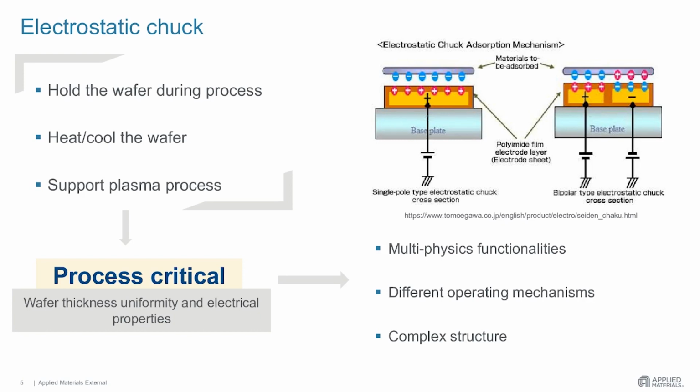And one additional function can be to provide heat to the wafer or to cool the wafer down, and do it uniformly, so the entire surface of the wafer sees pretty much the same temperature. So another complexity gets added where there may be a heating filament or a cooling loop in the electrostatic chuck.